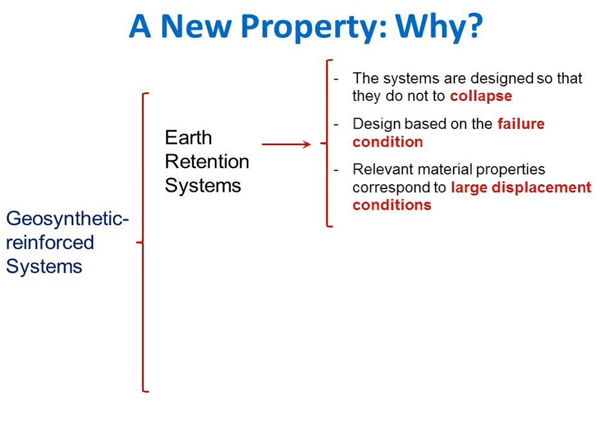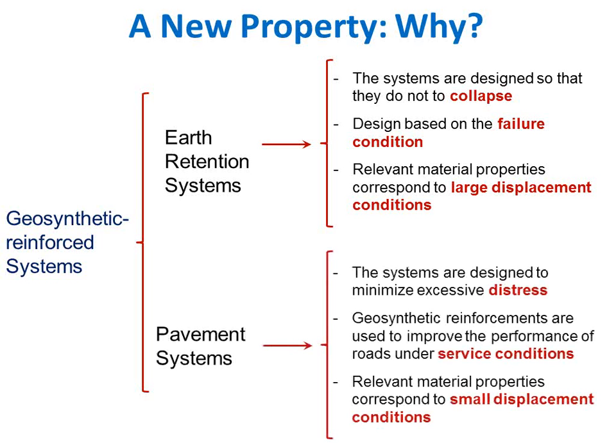That's very different than when we are dealing with a pavement system. As you may know, we are not designing a pavement. Actually, we're designing a pavement so that it will fail. If we design a pavement so that it doesn't fail, it's a bad design. So we design pavements so that they do fail, but we do it so that we minimize excessive distress. So this is a serviceability design.